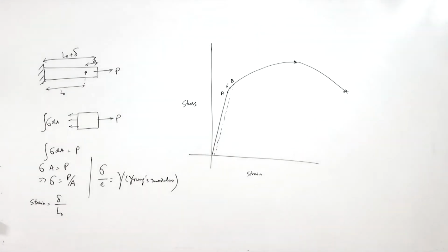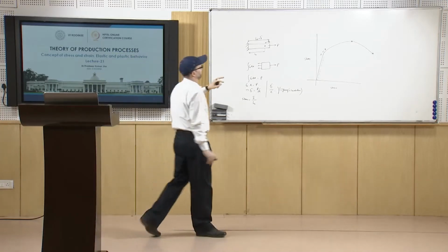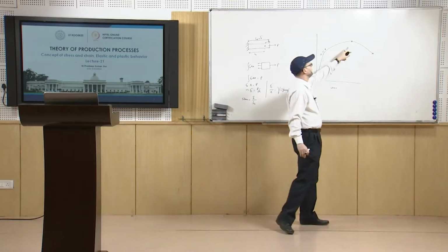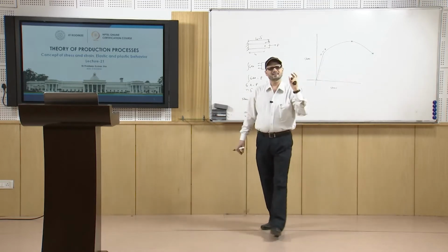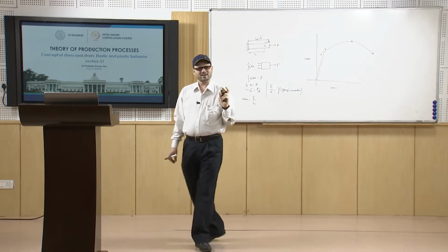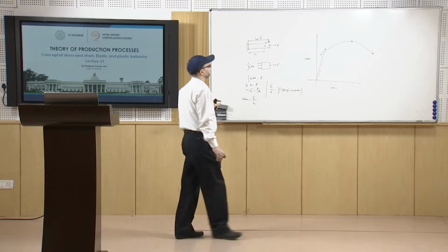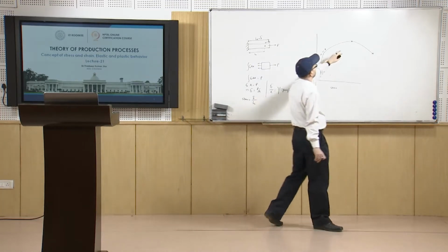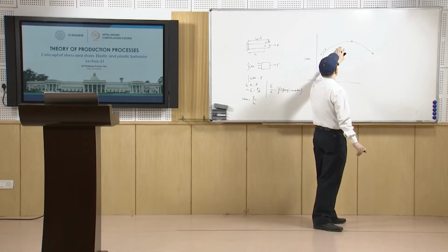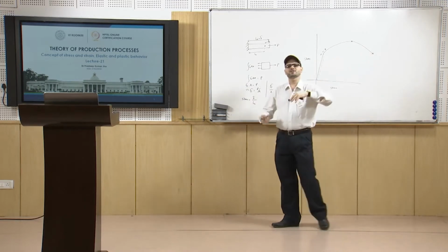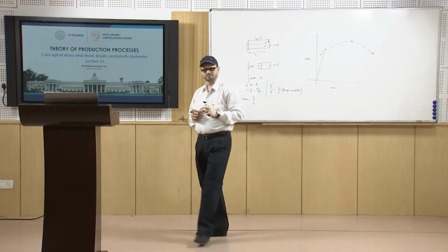So, that is your engineering strain, and that is what has been computed there. So, at this strain, basically after this point the necking takes place. Now, after that, for further deformation, the load is not required to increase; the load basically decreases.